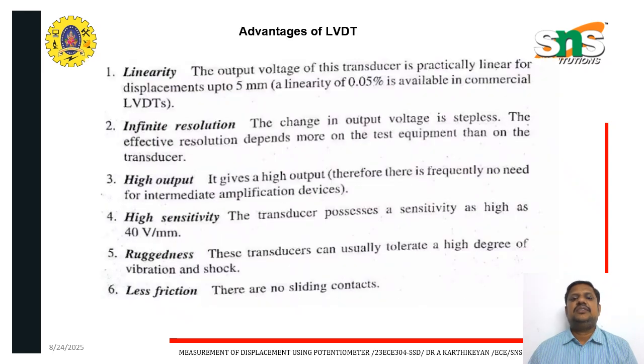There are six important advantages of LVDT. First is linearity. It has a linear value, so it changes with a very minimum level. Then infinite resolution, high output, high sensitivity, ruggedness, and less friction. There is no sliding contact. That is the main important advantage of LVDT.